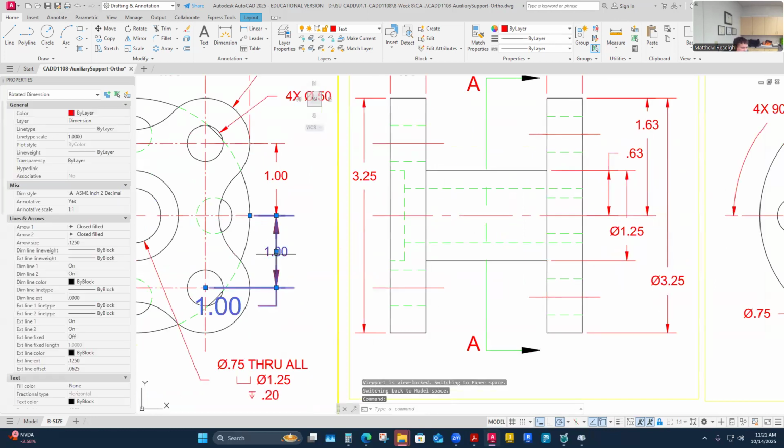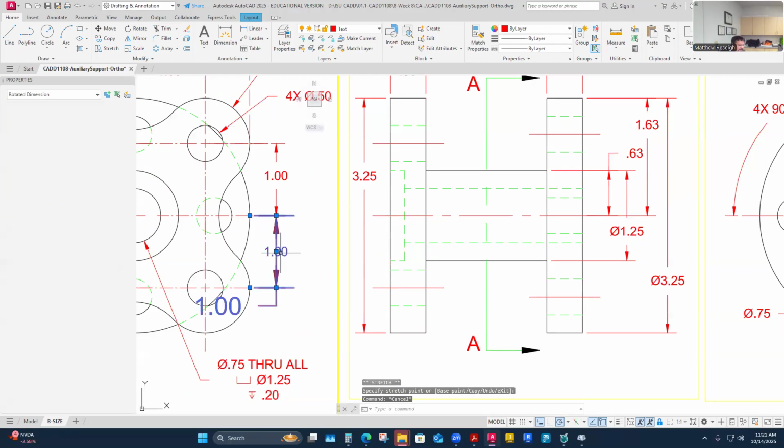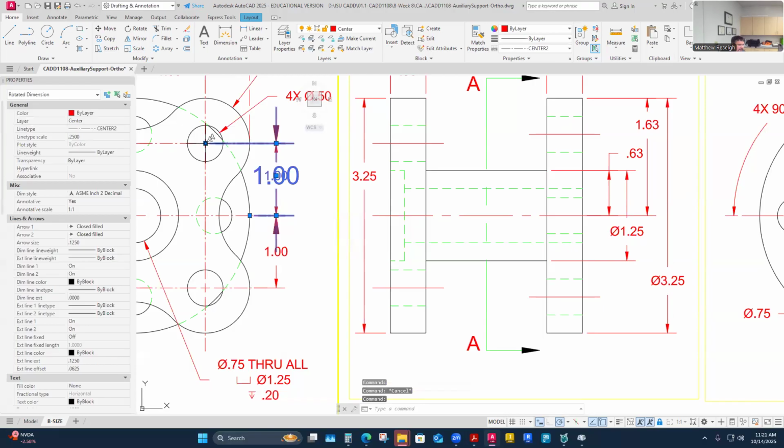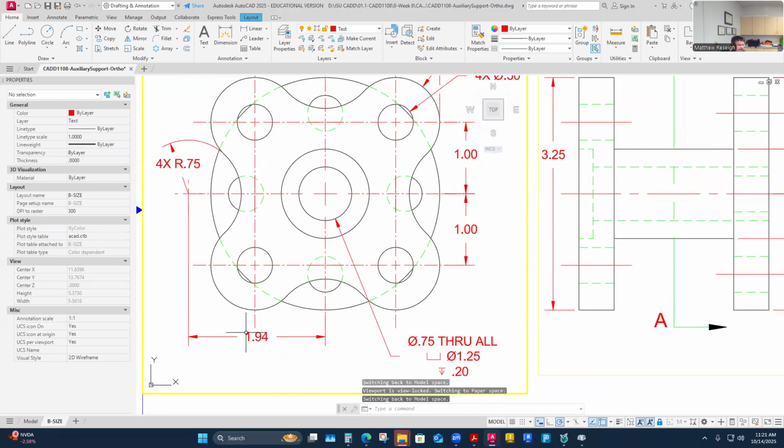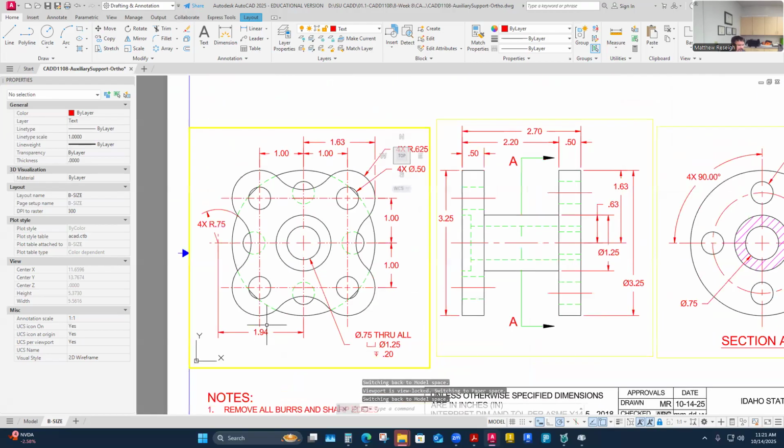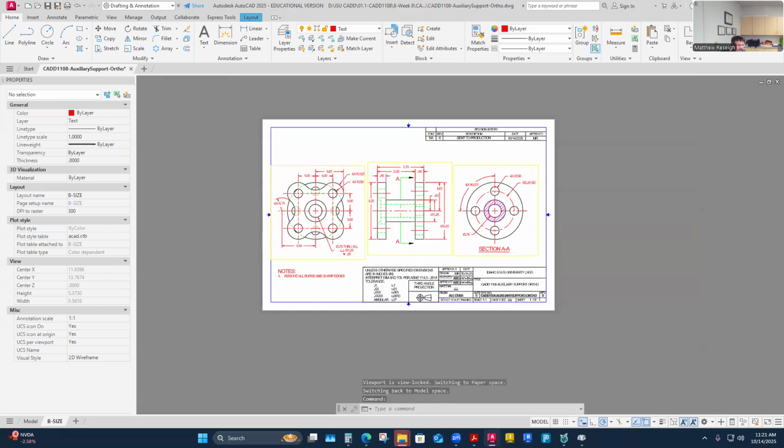And I'm just going to make sure that I pulled. See that one, I can tell I didn't pull. I call this out on a lot of people's prints, so they didn't pull those back to the object edge. Those leader lines, that one too. Those will always get you. I wasn't seeing the center line break up. I'm not going to break that out. I'm going to let that cross. That's okay. It's usually just the extension and dimension line relationship that I break. In fact, that might not even let me break that center line anyway.